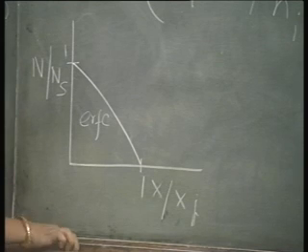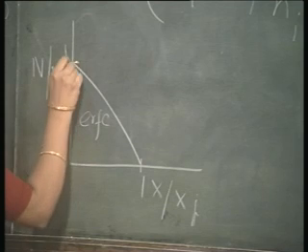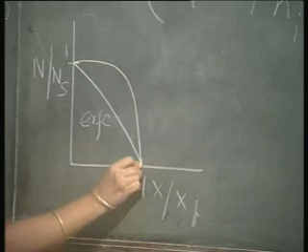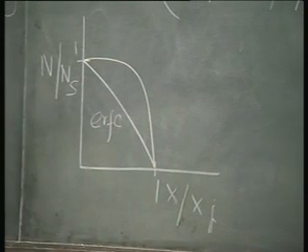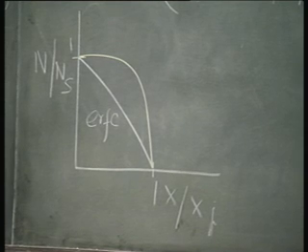So, if this is the complementary error function profile, and if this is what the arsenic diffusivity in silicon is, then it is going to follow a shape like this, right. This is going to be more abrupt.